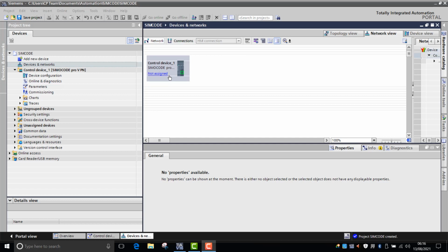Another reason why you might want to use active power monitoring is that you can use it for pump flow detection. For example, if the flow inside a pipe is decreasing, the active power would also decrease, which means that the pump could effectively run dry. So the idea is you can set a threshold which would indicate that the pump has run dry, and it could effectively trip the motor out.